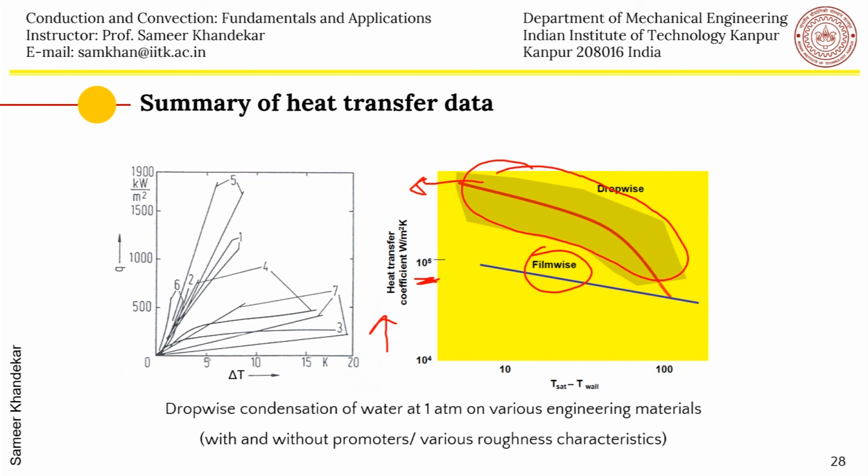So to summarize, dropwise condensation provides extremely high heat transfer coefficients, usually higher than the film condensation process. It involves the formation of numerous distinct drops. It is statistical in nature to a certain extent. There is a quasi-steady state which comes. After a while, bigger drops are formed. They keep falling, the newer areas are exposed, then new drops will be formed in those areas, and the cycle will continue.